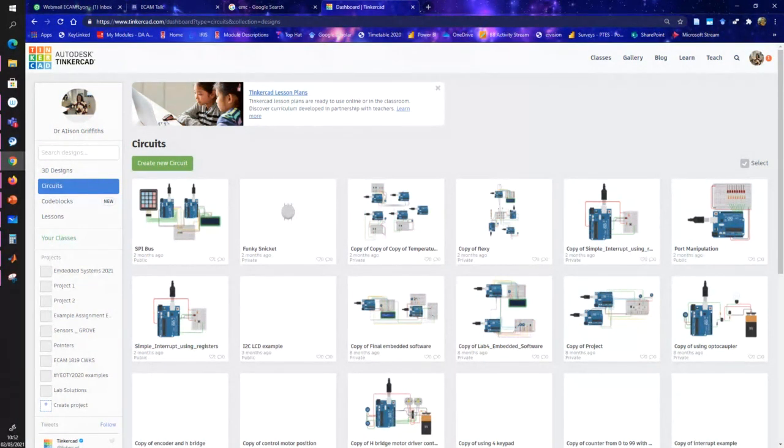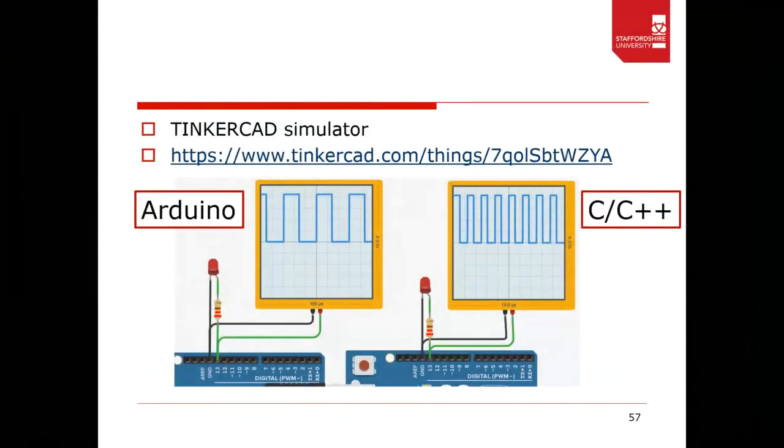So you say data direction register for port B that we're using, and then set zeros and ones, and a 0 is an input. Again, it's remembering which way is which. I think a 1 is an output, which is the same as the, yeah, I don't want to give you the wrong information. I will just share the right link.